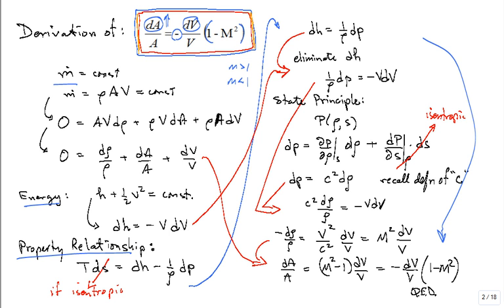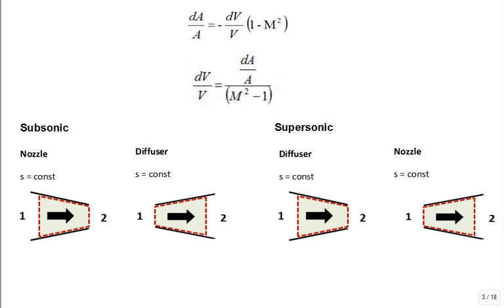Okay, all the mathematical tools are there for you. So if you have subsonic flow, flow in the direction of decreasing cross-sectional area, if it's isentropic, and all of these are going to be isentropic flow, it is our traditional nozzle. Things will speed up. V2 will be greater than V1. If it's subsonic and we have increasing area, then it'll slow down. V2 will be less than V1. It'll slow down. That's a bad looking V1 there, isn't it?